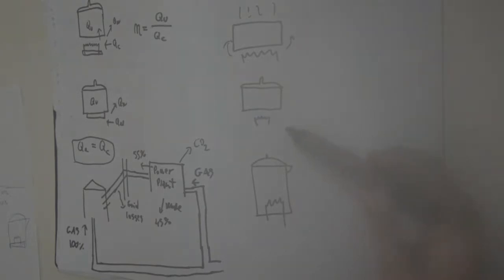For the electric kettle, it's a little different because I cannot just turn off everything that's in the house to measure this on the counter. So the best thing I can do is just read the power of this device and just count the time that it takes to boil the water, so that I read P, and I multiply by time, and I'll get the energy.